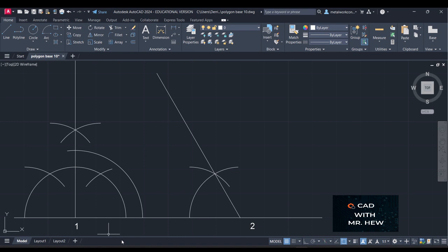What we're doing at 1, at the end of the line labeled 1, 2, is constructing a 45-degree angle. Is that clear? So we constructed this line, which is at 90 degrees. Then with the compass at 1 and any radius, we mark an arc which is greater than this semicircle, to intersect the baseline and the 90-degree line. So this is the line that we're working with. Good? Good job.